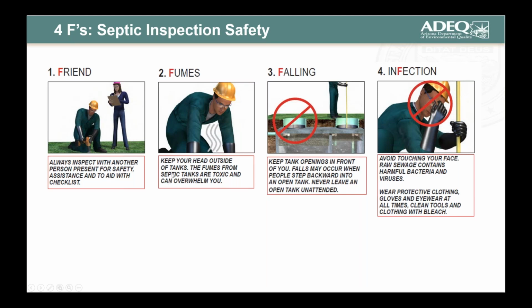Second, fumes. You need to keep your head outside of tanks. The fumes from septic tanks are toxic and can overwhelm you. Hydrogen sulfide is especially dangerous. You can smell it, and if it's strong enough, it will paralyze your olfactory nerve so you'll no longer smell it, and you could put yourself in harm's way. Generally, as long as you keep your head out of the septic tank, other than some bad odors and maybe some eye irritation, you shouldn't have any problems.